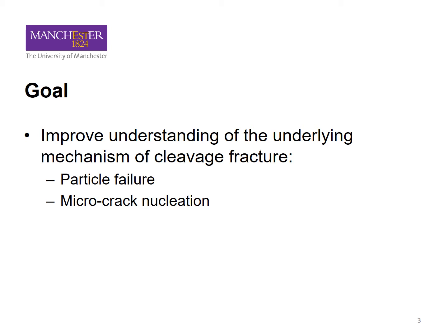The sharp crack within the particle passes through the particle matrix interface, and now you have a sharp crack in the material, which can then propagate. Propagation is generally assumed to follow a Griffith-like process, dependent upon the particle size and the critical stress.